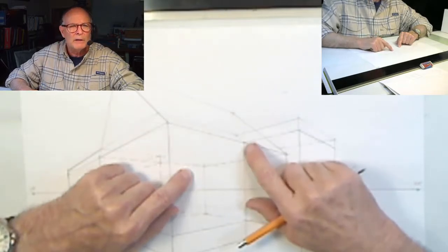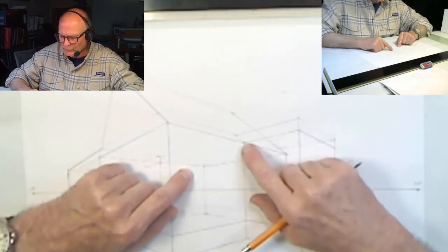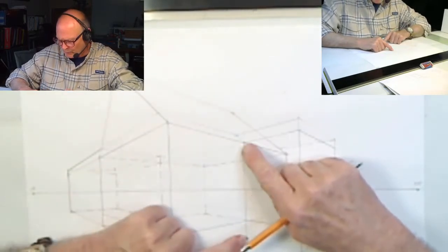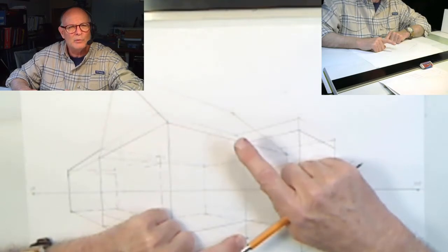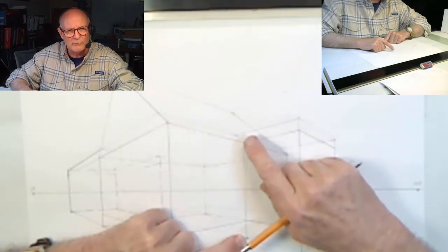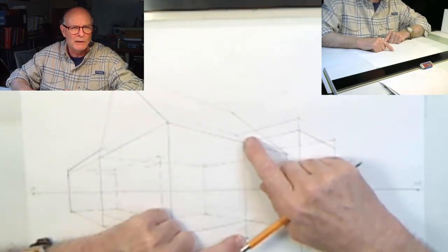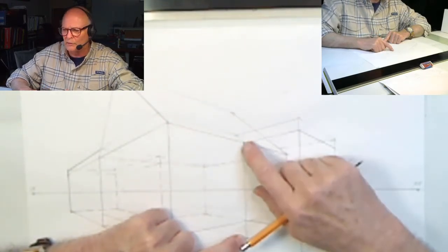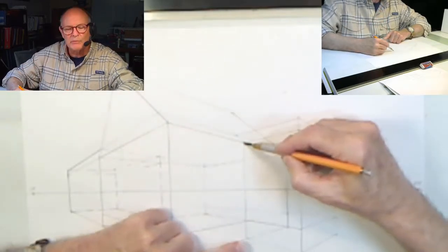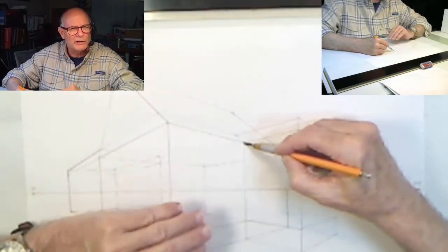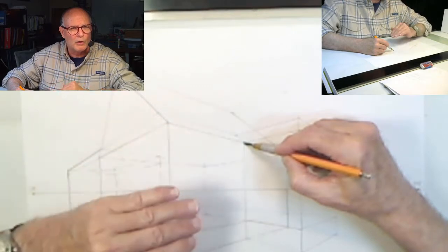After we found the halfway point, we were able to extend a vertical line up from the lower portion of the main building to the upper exterior wall, and that created this vertical line intersection. With that in place, we know that it becomes the transition of slope between the vertical wall and the sloped roof.